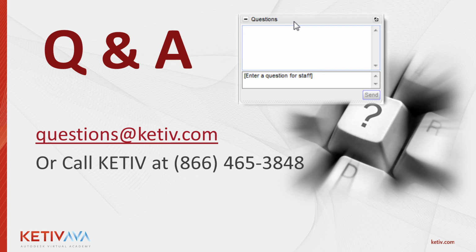Certainly. There's another Vault question. Can I use Vault AutoNumbering schemes with these dynamic file names that you've used iLogic to generate? So that's one of the areas that is the caveat. With the Vault AutoNumbering, even with the Vault API, there's not a whole lot we can do with that. But since we're doing this all from Inventor, there is data standard. And data standard is a way to extend the interface and some of the capabilities of Inventor, AutoCAD, and Inventor. So we can absolutely use data standard to tap into the Vault numbering scheme and then pull that into our automation. So that's definitely a possibility.